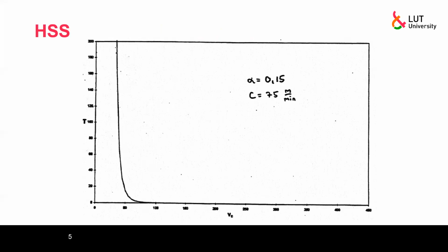So typically, things like this are calculated. So it is a curve of if we increase cutting speed here on the horizontal axis, then what is the tool life, which is on the vertical axis, and this is an exponential curve that approaches 0 as cutting speed approaches infinity, and the hexagonal curve means how much play we have here under the curve to select our parameters. And the C, typically in these formulas, is a reference time of what's the speed, so that the tool lasts for 1 minute or maybe 15 minutes, depends on those. And alpha is a factor telling the slope of this curve.